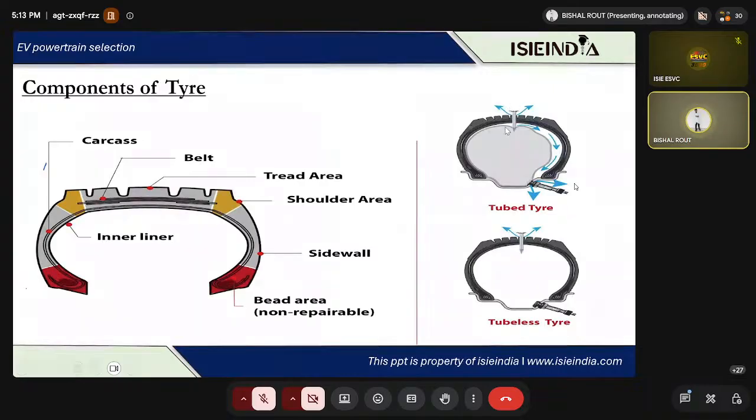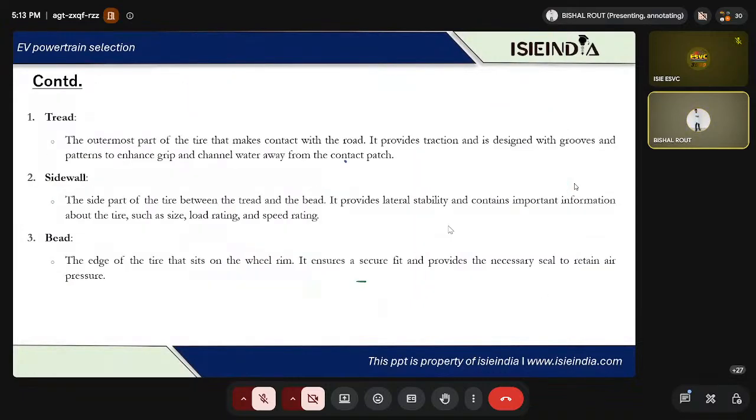Then you can fill the air inside the tube. But if there is no tube, there is no need. If you can normally seal it, if you can block the hole by suction, then the air stays in easily. That is why puncture repair for a tube tire takes time, but for tubeless it won't take much time. But this requires skill, this tubeless tire.